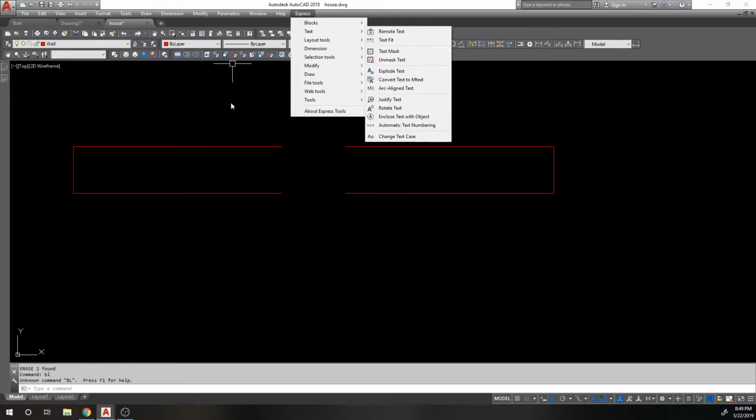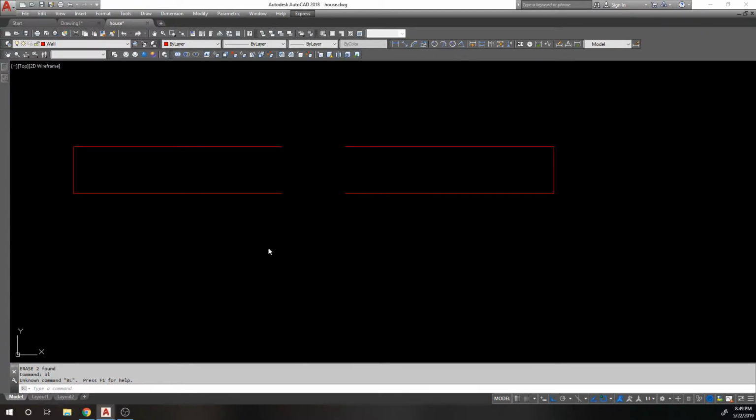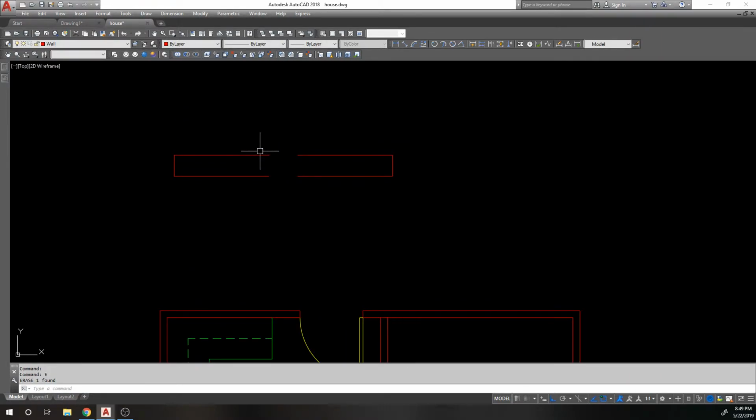I thought I had Express with break lines. I probably don't have an alias set up for it, that's why. There we go. So I'm going to set my break line size for 2 and an extension line for 1, and let's see how that works. Break line is part of the Express Tools command, and that's not at all what I wanted. Break line size. Oh, because break line is modified by my dimensional scaling. I'm going to put this on standard, because standard has regular scaling.